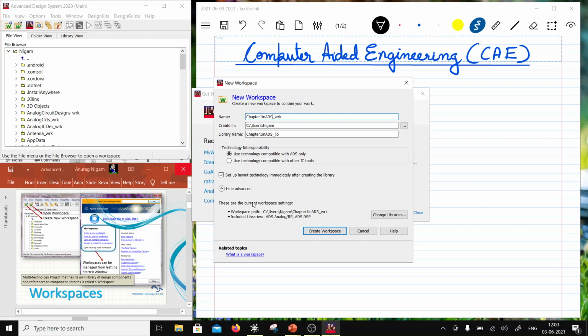One is the native flavor, which is basically a PDK done explicitly for ADS, and then there is something called GPDKs, general PDKs, or they are called IPDKs or interoperable PDKs, right? These would have a different UI, so you have to click that if you are using a GPDK. It's just going to change how things are displayed on the schematic and stuff like that.